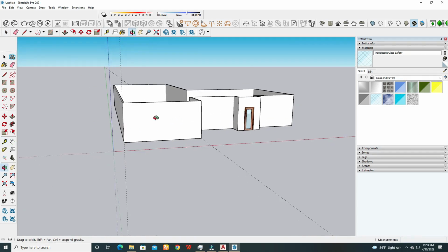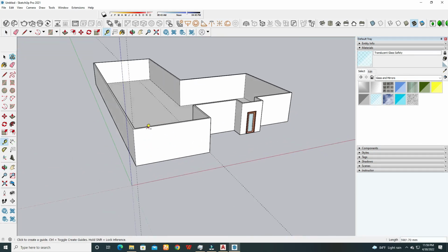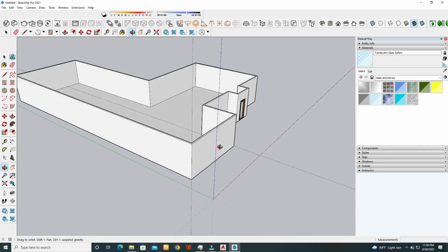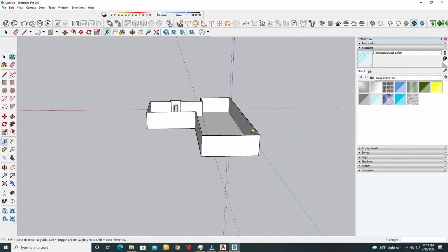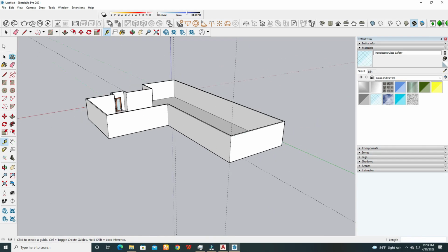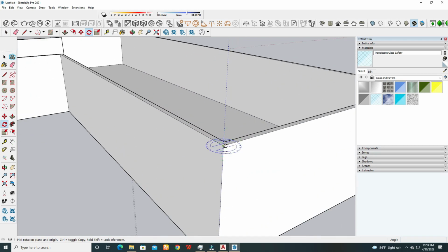Okay, I'm just going to make only a part of the roof. Only this part. Like this part. I will need to get this one. Press this like this. Now select this reference line and get the rotate button. Now you see that when I try to place this rotate button here, it goes along different planes.